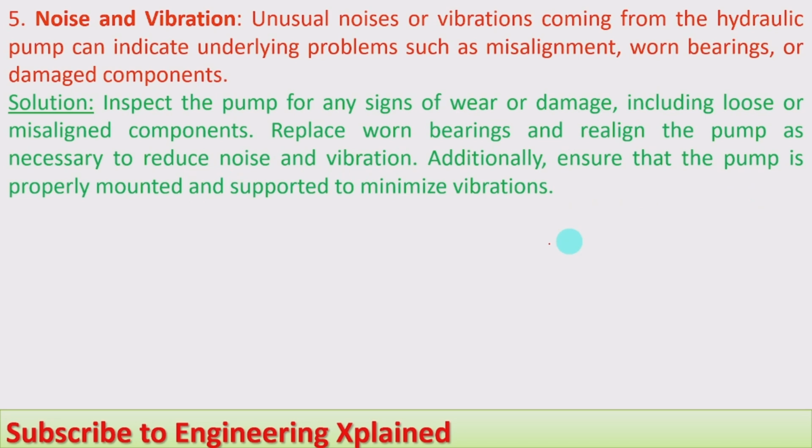Additionally, ensure that the pump is properly mounted and supported to minimize vibrations. The pump is to be mounted on the foundation properly, and all the components should be aligned during the rotation, and the worn out part should be removed. In order to remove or repair, something should be done for reducing the noise and the vibration.